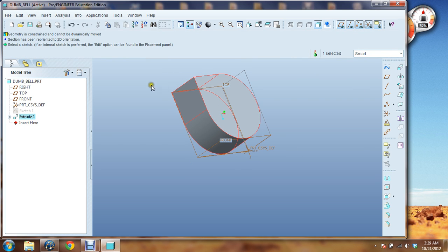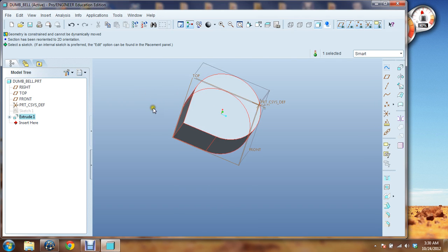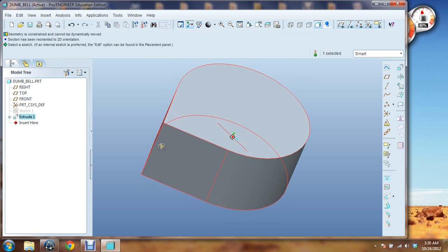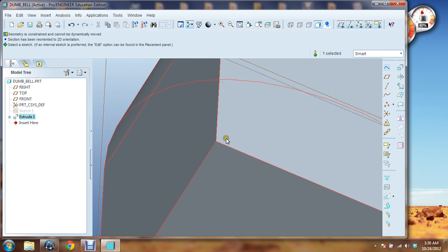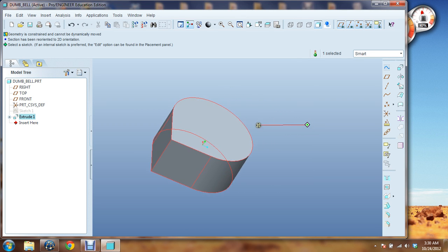And I want to point out now, you saw me rotating around earlier. Probably should have explained, just like in the sketch, if you click and hold down the middle mouse, you can rotate and check out your part. You can also zoom in and out just like with a sketch using your middle mouse wheel. We can zoom in and check out certain parts. We can see what's going on if something's maybe not quite how we want it. And then we can also pan, so we can hold down Shift and the middle mouse and pan from left to right.